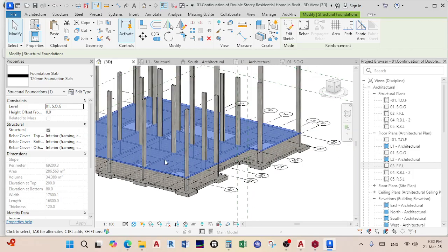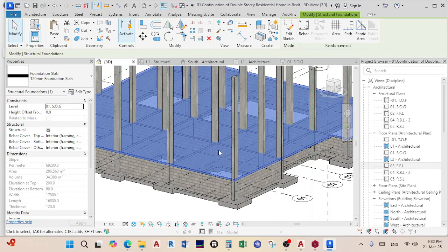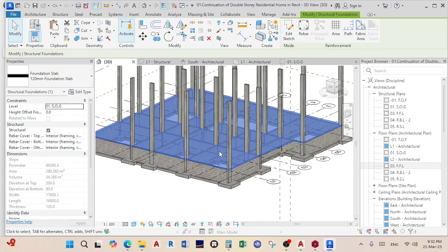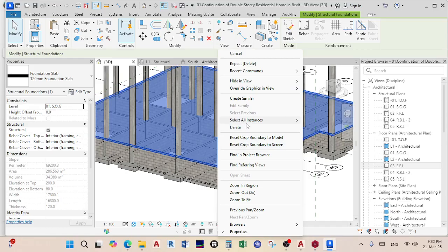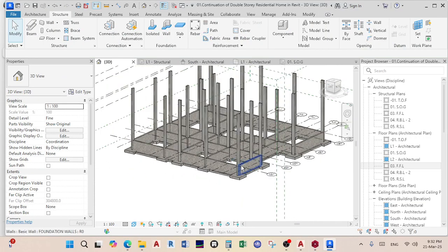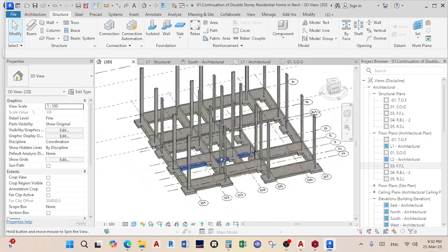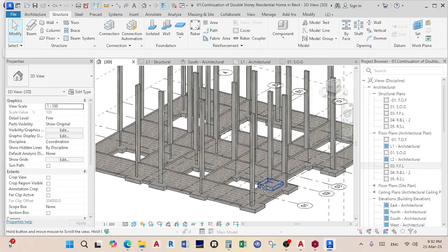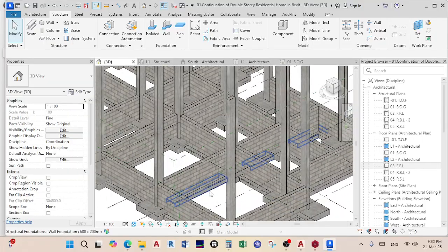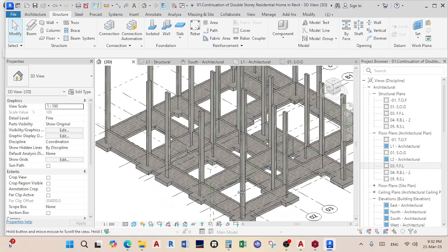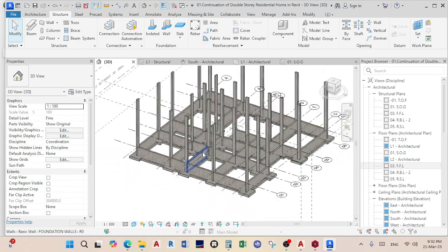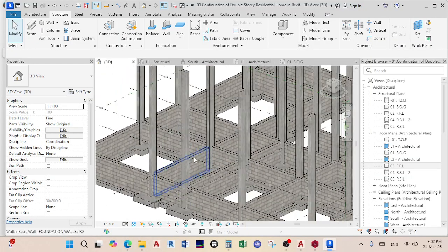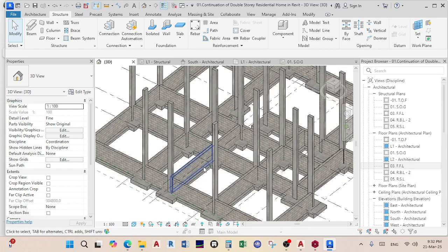So it's entirely up to you. As you can see, we've created those, the Zambians call it the box, right? If I hide this, for example, when I go to hide view and say hide element, it hides the slab. Now from here you can see what's happening realistically: we've excavated into the earth and put up this 600 by 200 thick strip footing, and on top of it we've built these walls, and these will be helping transmit the loading of the walls on top, right?